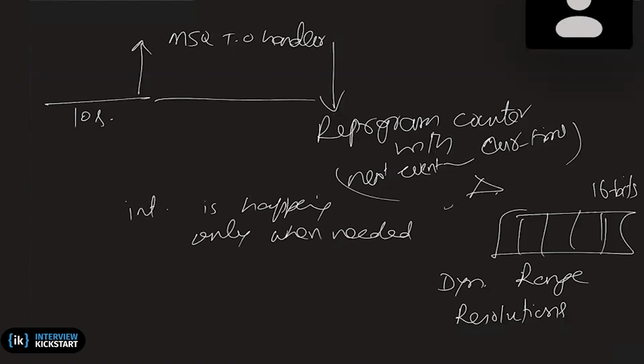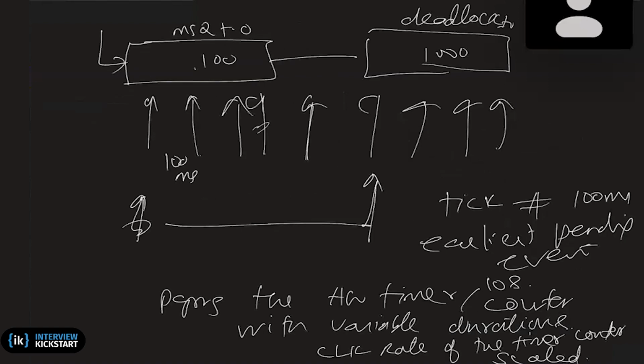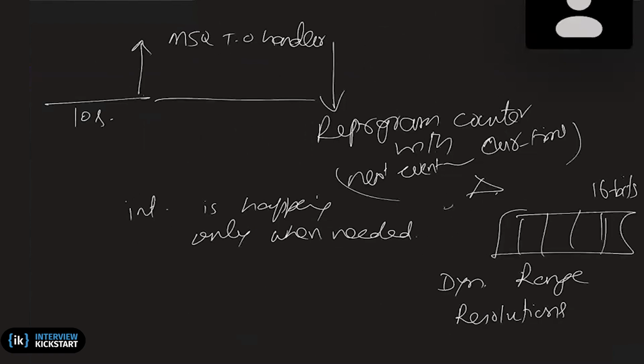So that is why it is called tickless programming. If you see this picture, the ticks keep coming, even though you don't have any event changes, except the interval is shrinking. So this is tick. And in this case, the tick comes exactly when that event expires. So it is basically tickless programming in that sense. But actually there is a tick. That tick happens in variable intervals. And so I would like to call it dynamic tick. And this is more popular terminology.